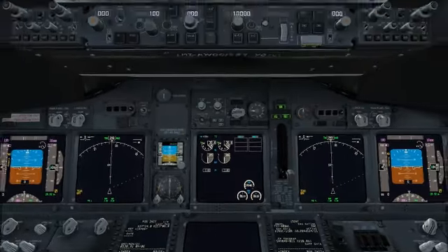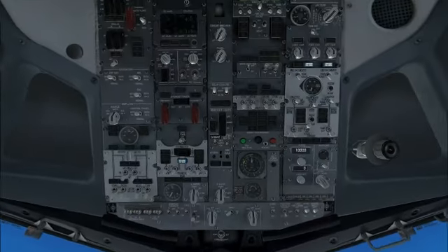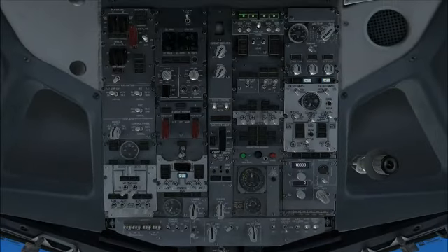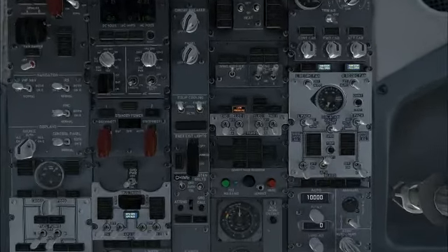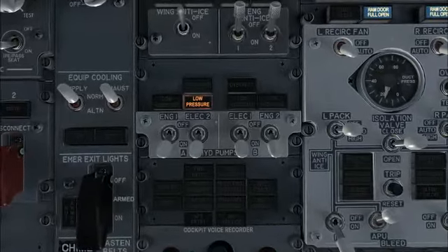The 737, like many other airliners, is based around a dark cockpit philosophy. This means that system annunciator lights in the cockpit should be extinguished while those systems are functioning normally. Logically, this means that lights will only illuminate when there is reason to draw crew attention to that system. This reduces distractions during normal operation and draws immediate attention to conditions which must be addressed.